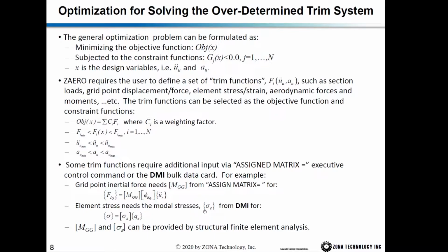What are modal stresses? In ZONA's ZAERO, if you use Solution 103, which solves the eigenvalue and eigenvector of the structure and gives you the mode shapes, then you can ask NASTRAN to treat each mode shape as a deflection. Then under this deflection, you can ask for the stress in a given element.